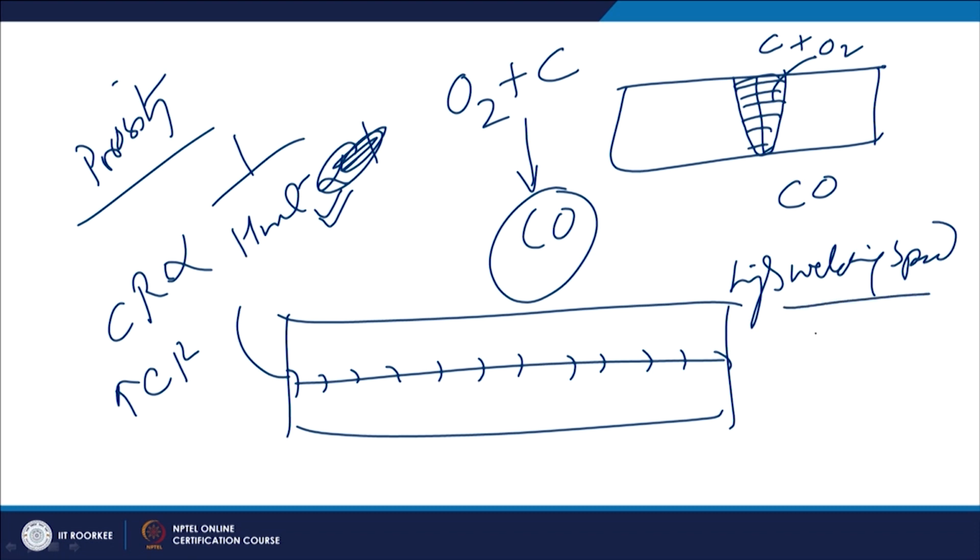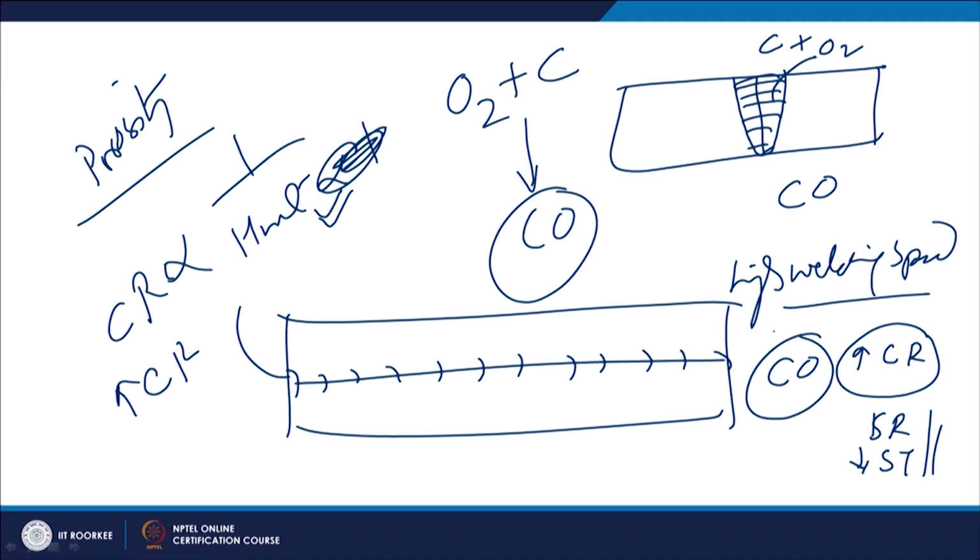If these two are combined during the welding of low carbon steels which are rimmed or capped type, then the carbon monoxide, due to the high cooling rate conditions, the weld metal experiencing a higher solidification rate and reduced solidification time, leads to the entrapment of the carbon monoxide gas in the weld metal itself, because it does not get enough time to escape. That is how it leads to the development of pores.